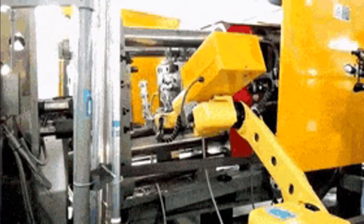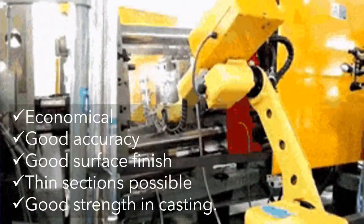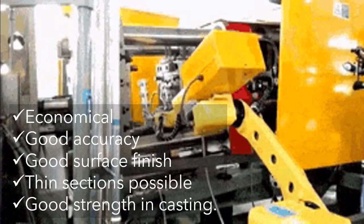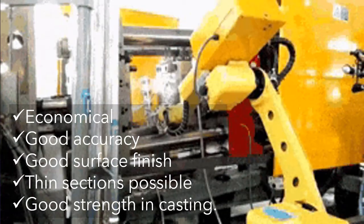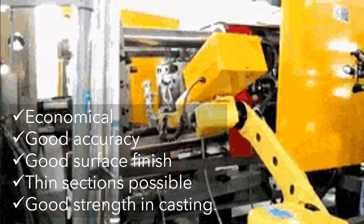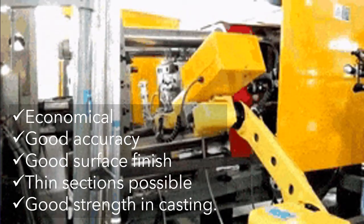The main advantages of the die casting process are, first, it's economical for large production quantities. It has good accuracy and surface finish. Thin sections are possible, and rapid cooling means a smaller grain size and good strength in the casting.